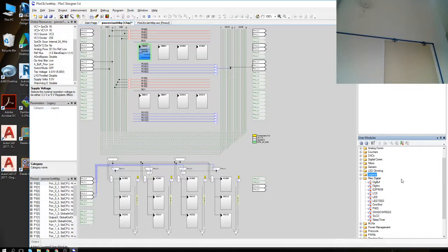Okay. So if you just invert that pin, you actually need shadow registers, since you cannot just read the pin and rely that its logic value is 1, although you have been writing a 1 there. Those are different. They can be different, and they most certainly will be.